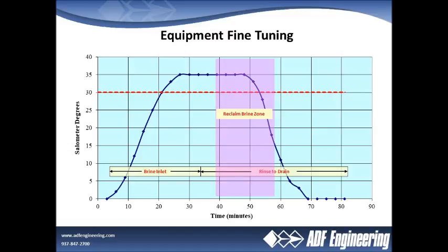the water from your softener regeneration process, because softeners typically regenerate every 8 hours and they operate 24/7, 365 days a week. There's thousands of gallons of water that can be reused using this approach, and it doesn't require any amount of extended treatment. Sometimes we put a filter on the line to catch any suspended particles, but that's the extent of it. So the payback is pretty quick usually.